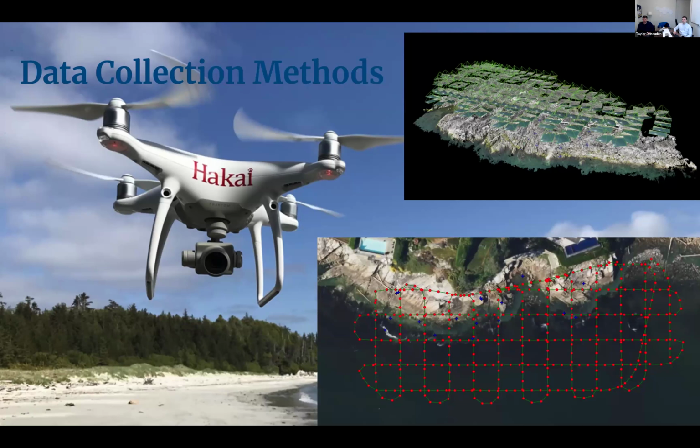And we use structure from motion software. So we use either Agisoft Metashape or Pix4Dmapper, and it takes the imagery, looks for tie points, so matching points between images, and turns the individual photos into a 3D point cloud, and then an orthomosaic and elevation model.